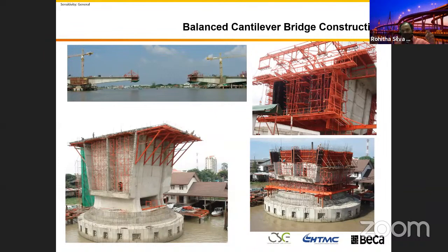The three-span continuous bridge, when you place the load in, the variation in the bending, because what are the additional loadings when you pour the stitch pour in this balanced cantilever bridge? What you're going to get is your traffic load and the barrier load and other loads. So therefore, this bridge design and construction, and if you look at the behavior, they are very different.